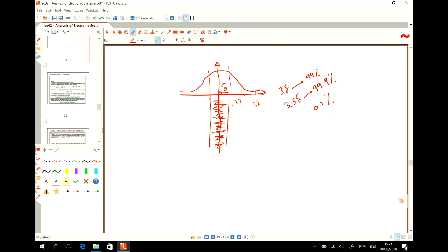And then 3.3 multiplied by 2 is 6.6 times the RMS. If we say that the RMS is sigma, then 3.3 multiplied by 2 is 6.6 times sigma for the peak to peak. So for the random process, this is how we can say that I'm interested in only 99%, then it's 6 times. Then we say that the peak to peak is 6 times. Okay? Clear? All right.